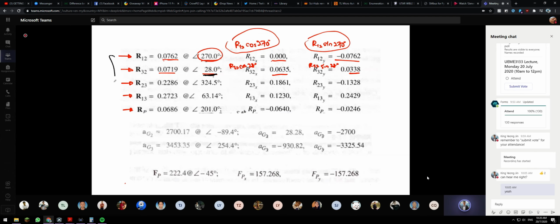So even though I show you, this seems to be very straightforward, but in order to find this, find this, you have to make a lot of sketch and calculation. So once we get these two values, then we can straight away find R32X, R32Y. So again, R23 is given in the question. So that is the center of gravity 228.6 mm at the angle of 45. So again, you have to recalculate the 45. Right? So in this case, if we refer back to the